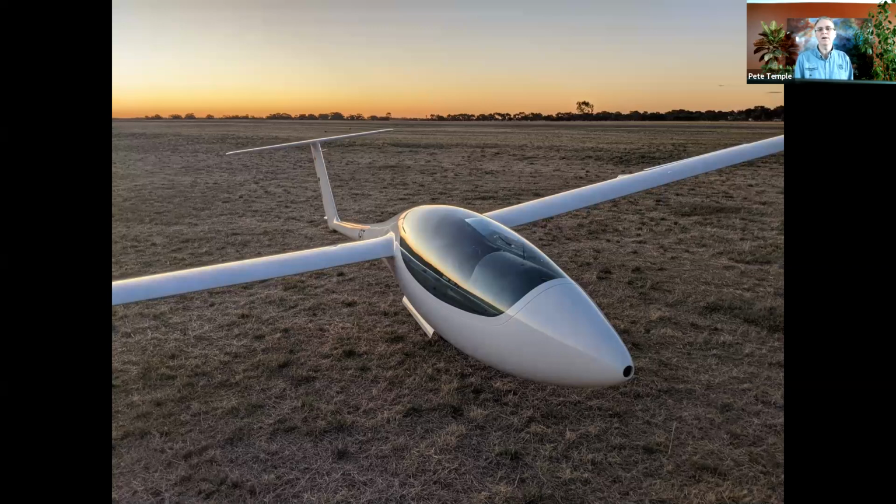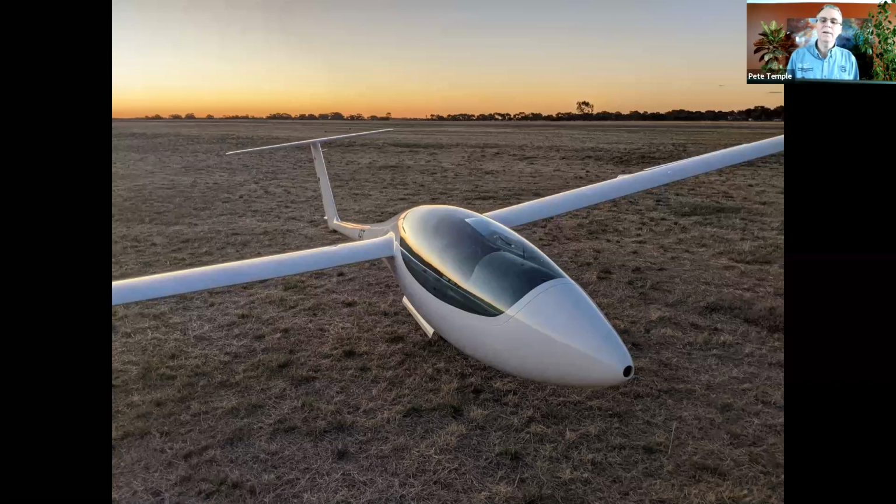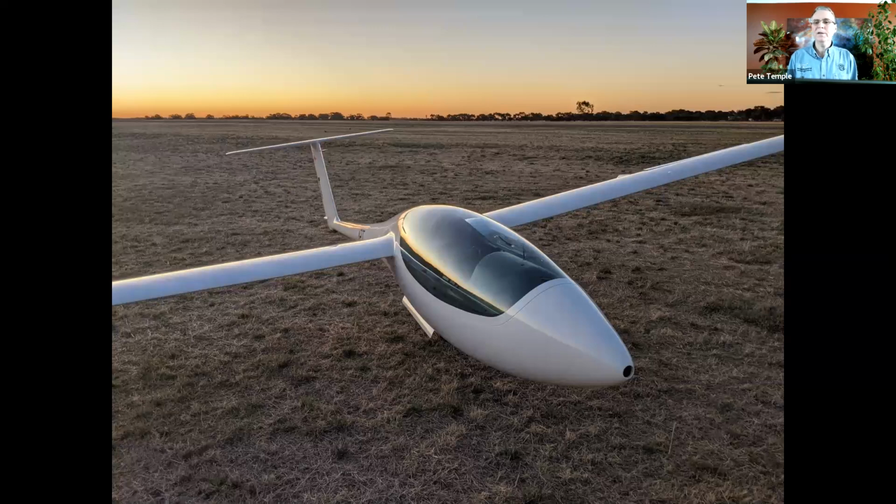We actually put a safety height in, and we aim to come home higher, so if something goes wrong, then you have a little bit of height up your sleeve, and you can still make it back to the home airfield. I tend to use something like 500 to 1,000 feet. I can't remember what I used on this day. It's not absolutely critical, because if we don't make it back to the home airfield, there are other places we can land. It's not very convenient, because somebody's going to have to go out and fetch me. But if I don't make it back to the home aerodrome, I can land elsewhere.